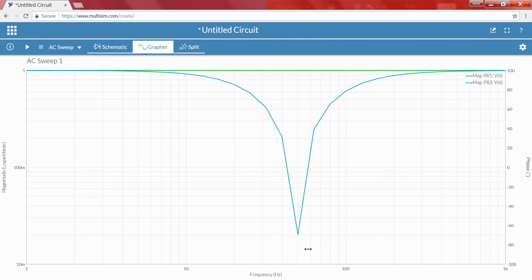The reason is that we are looking to eliminate only the 50 hertz noise, and we do not have to remove other things. So, rather than going with a long range of notch filtering, going with a narrow band filter would be really advantageous, so that it only removes the 50 hertz frequency signal. Now, this looks similar to our narrow band frequency response.